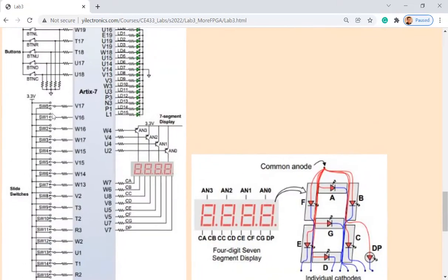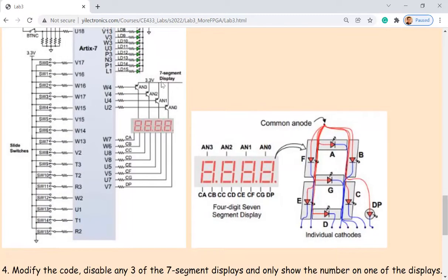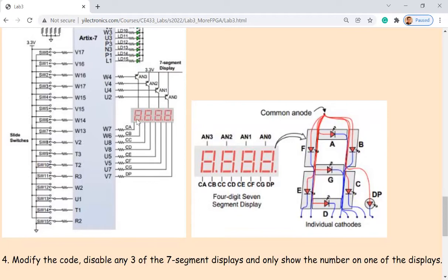You're not building this circuit, right? This is the Artix-7 FPGA on the Basys 3 board. It's just showing how these anode activation pins work with the Samsung display modules. You don't need to look at these ones, right? Just this part. You can activate each display digit individually by setting this bit to 0. If you give a 0 here, it allows current to flow through this display module and turn on the whole module. Okay.